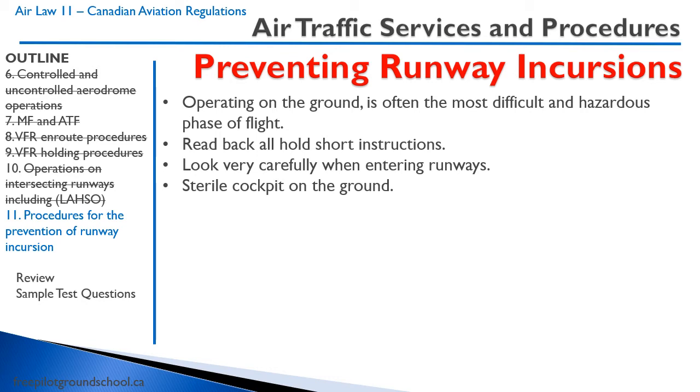When you cross or enter runways, you take a very good look out to the left side and to the right side. Think of it similar to the way a school bus driver stops at train tracks. Now, you shouldn't be stopping because you'll hold up traffic, but take a really good look out. Also on the ground, it's important to have a sterile cockpit. Don't talk. It's time to pay attention and live up to the task at hand as opposed to chatting about whatever thing is on your mind.